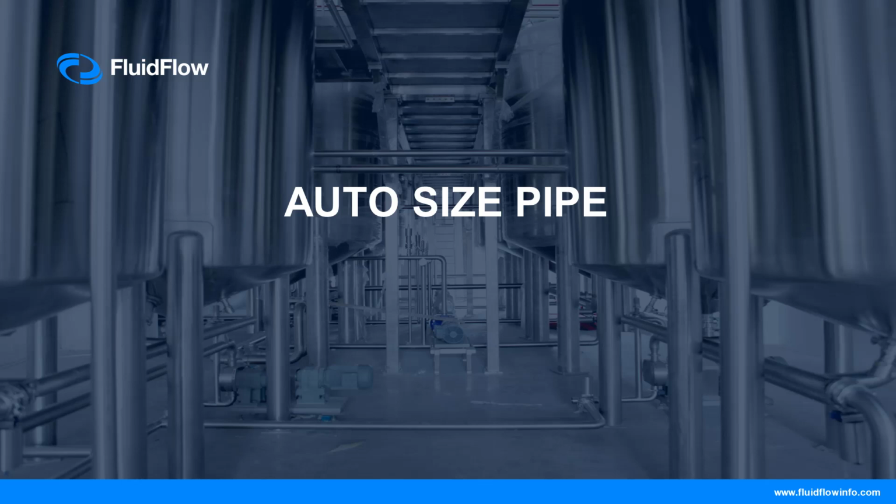After this, we know how to set the flow with the known flow component. We've experienced an example demonstrating the need to specify the pressure in at least one boundary. We observed how to use the results from the auto-size pipe feature to size the pipes and how this cleared the warnings due to high or low velocity. Also, we further discussed the warning messages that appeared during the process. In the following video, we will show how to model controllers to get the desired flow instead of using the known flow boundary.